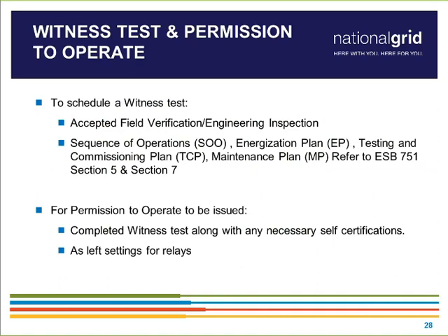Okay, yeah, good point. And those will all be discussed during the construction calls that we have. We may tell you that one or the other may not be required, but if it is required, you know where to find them, give you a good start. And then once we get through the scheduling of the witness test, we go through it. Once it's successful, we'll give you permission to operate. And along with that, we'll get sign off on the actual test plans. We'll run through them during the witness test and then take down any as-left relay settings.